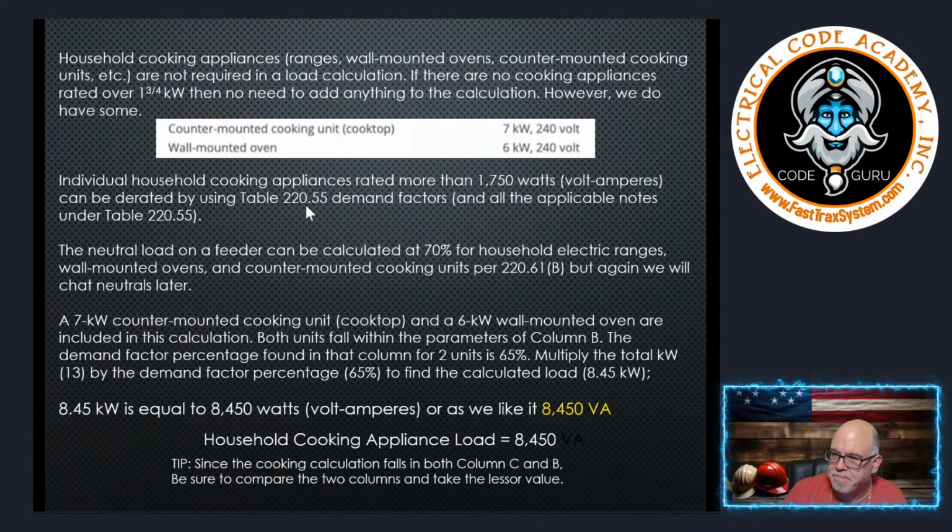220.55, right? Now, I'll remind you that once we do this, the neutral load also is the same as we just did for the dryer, 70%, okay? So it makes it easy, right, to do the neutral. That's why I like to do it as we go.